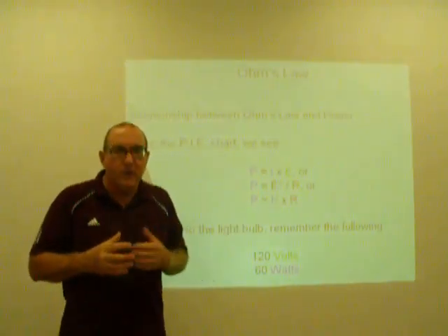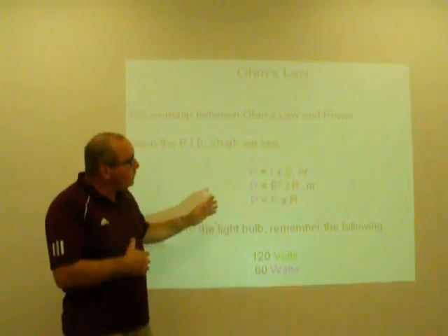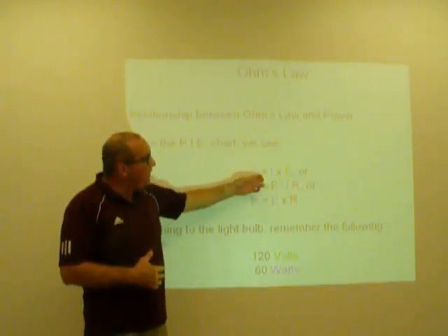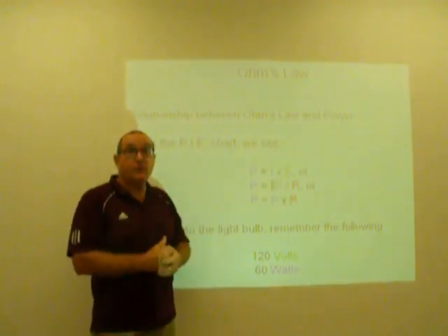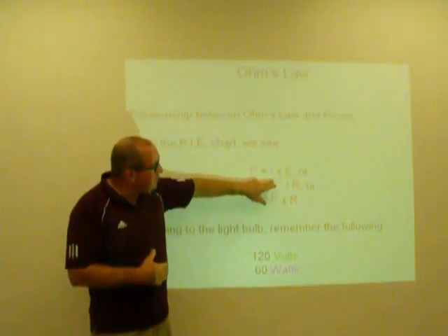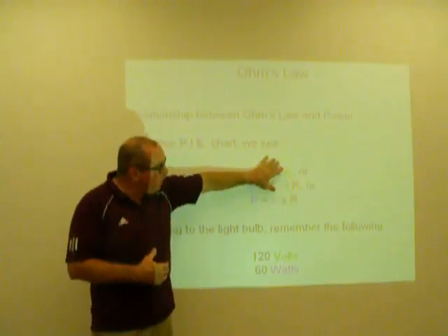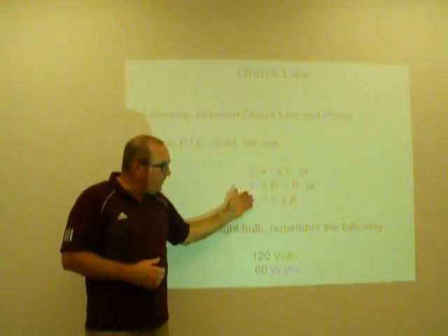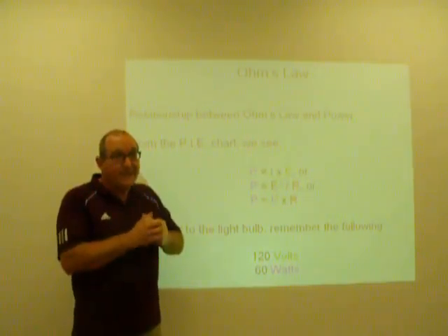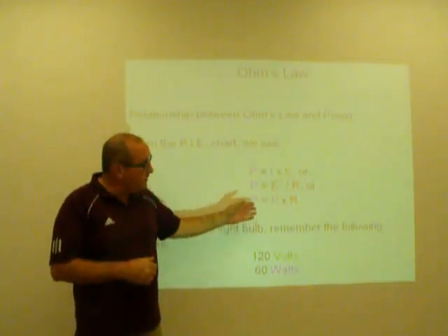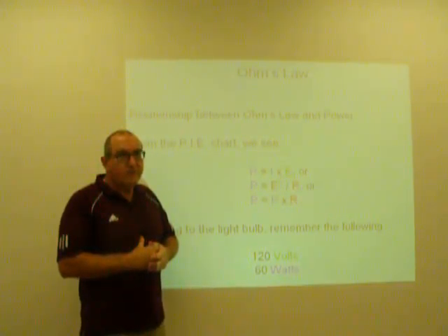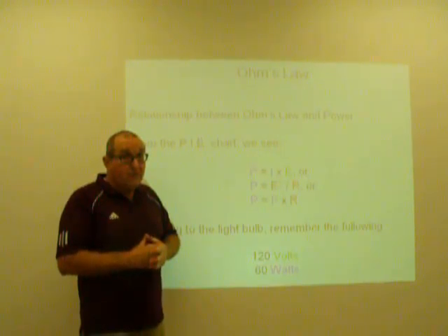The relationship between Ohm's law and power: we have determined through experimentation and other methods over time that power equals current times voltage. Now, you can put this into Ohm's law and substitute I or R or other quantities, and you'll get one of these other equations. This equation itself is extremely important to the electrical power generation industry, because this is one of the reasons that they generate electricity at such tremendously high voltage, tens and hundreds of thousands of volts,